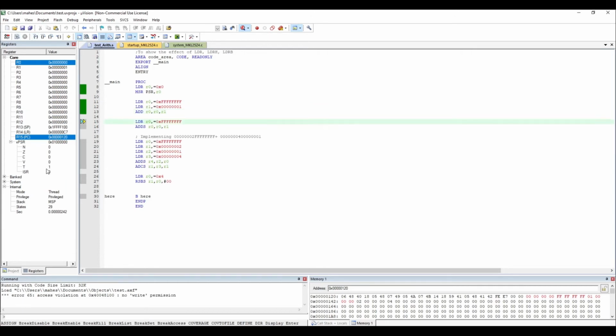Okay, nothing is changed in the flags. You can see R0 got changed to all zeros because I added these two, there is a carry overflow with the result being 0, right? That's a big thing which happens in many places in computation. If I don't consider the carry, literally it means that R0 becomes 0, but that's wrong, because there is a carry overflow, so you should consider that it has gone beyond the 32-bit representation. That's what happened. Now let's redo this with ADDS, not ADD.